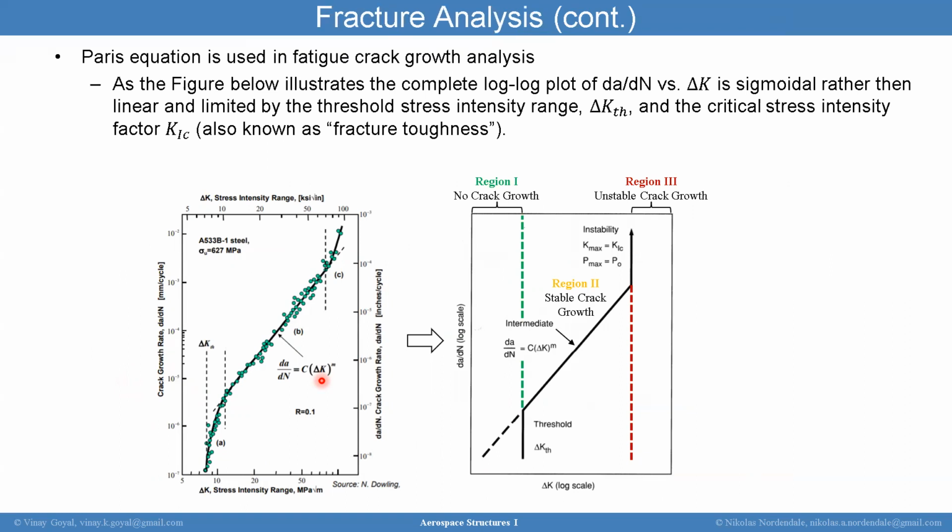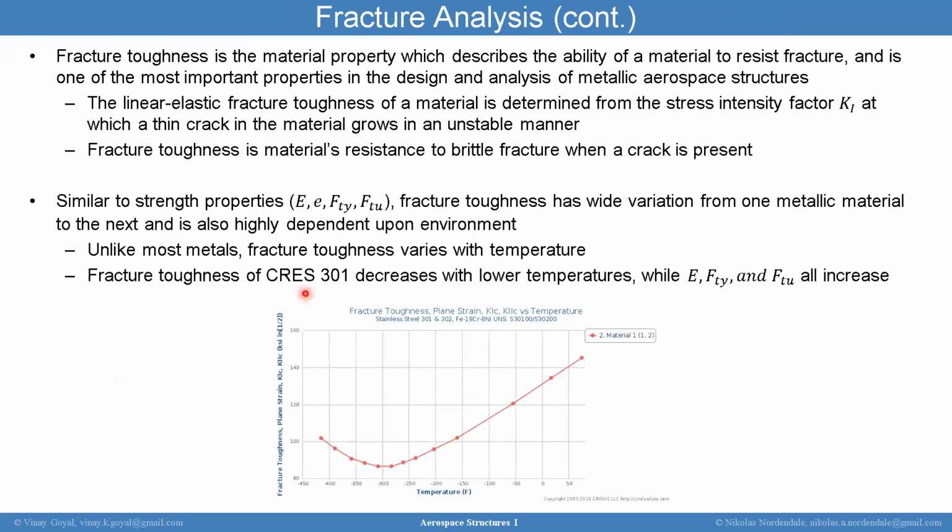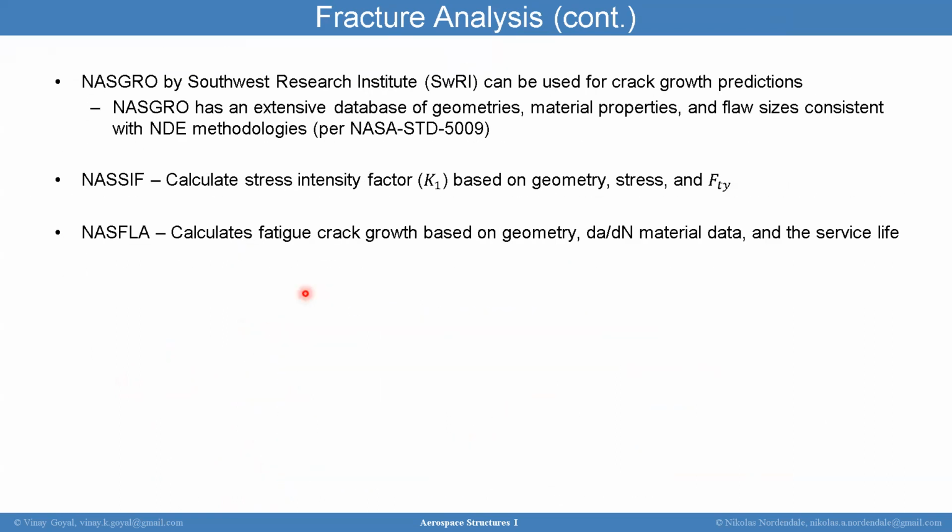When you have multi-cycle loading, then you want to go into something like this where you have cyclic loading occurring, and that's going to tell you a lot about what the crack growth rate is. It's going to tell you whether the structure will survive, because the crack growth will continue to increase as you cycle it, and so that's going to help you with that.